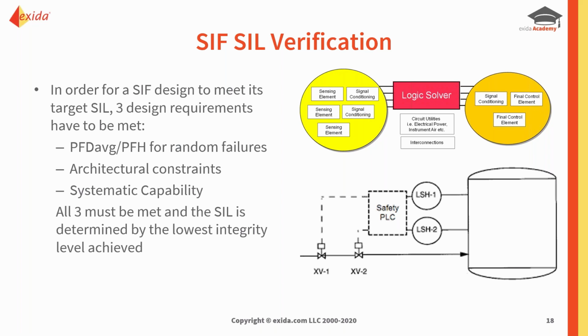The second thing is the architectural constraints. And the third, of course, is the systematic capability. So all three have to be met. And of course, the SIL that's determined is from the lowest integrity level achieved. So this is the crux of this.